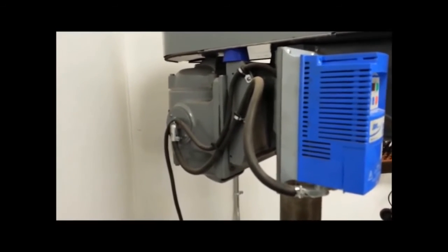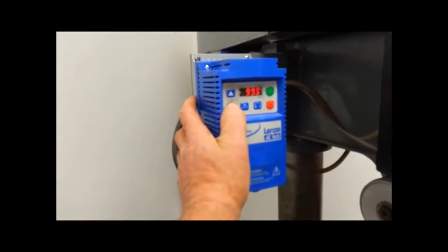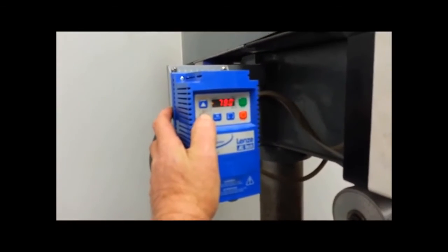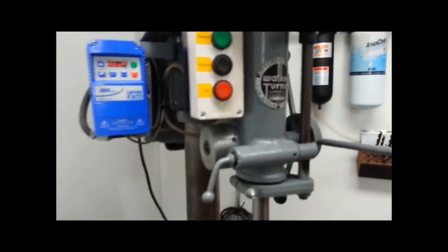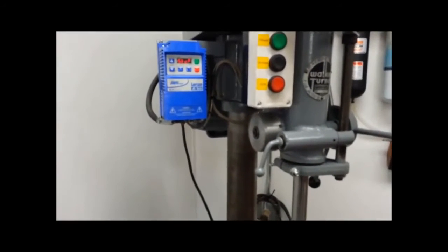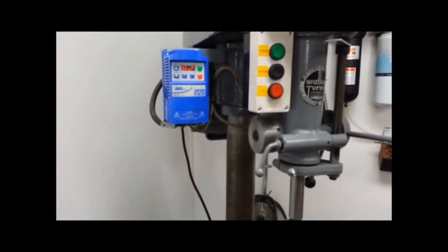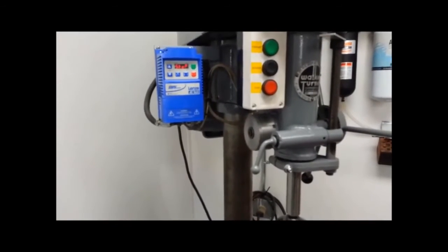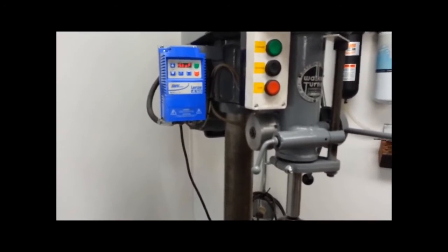Service factor amps is the point where you need to go into overload and alarm and not pull any more than that. Service factor amps is basically an alarm condition. Running amps or tagged amps, not including service factor, is normal, and I would never exceed just the tagged amperage.